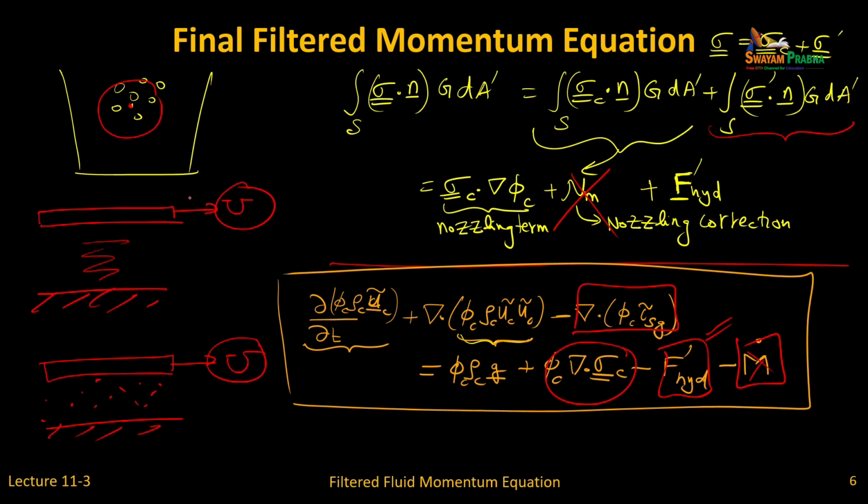So, when there are particles, effective viscosity changes, and that's what we derived as Einstein's viscosity correction. And the same thing happens, instead of pulling the plate, low temperature, high temperature, just fluid, fluid with particles, conductivity changes, heat transfer increases, or can decrease, depending.